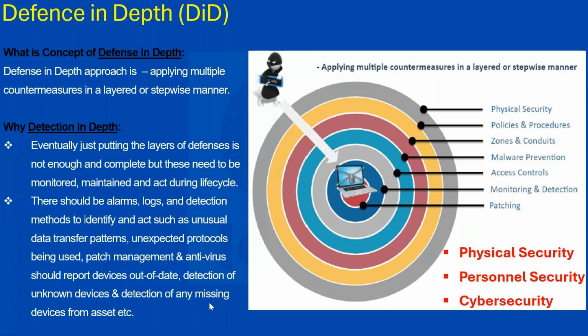Whatever speed of data transfer is needed, it should work, because in the industrial sector, in operations technology in particular, it is a matter of even milliseconds. We work on 100 milliseconds, 200 milliseconds of response time, and this is what makes it more unique. So whatever system we put in place, we have to make sure that our control loop, our process control, is not impacted by these deployments.